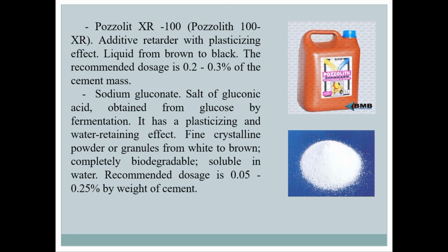Sodium gluconate, salt of gluconic acid, obtained from glucose by fermentation. It has a plasticizing and water-reducing effect. Fine crystalline powder or granules of white or brown color. Biodegradable, soluble in water. Recommended dosage is 0.05–0.25% by weight of cement.